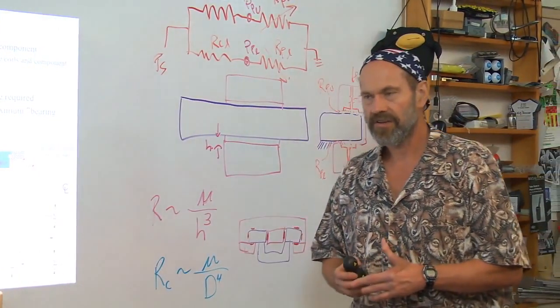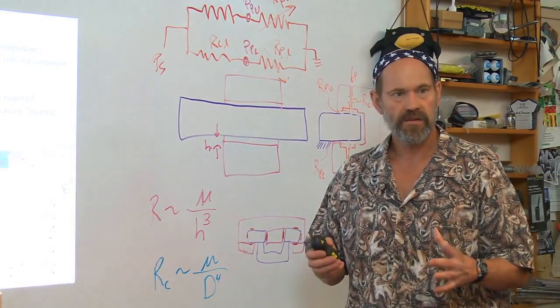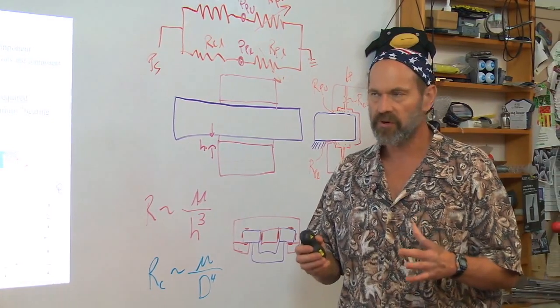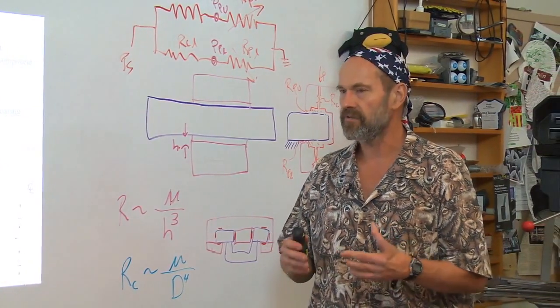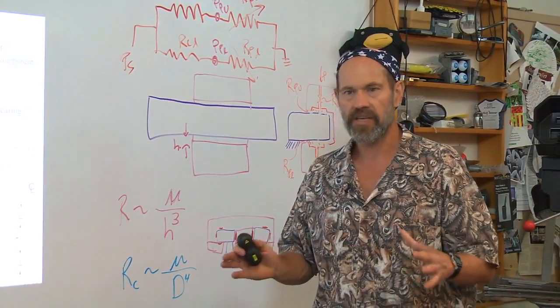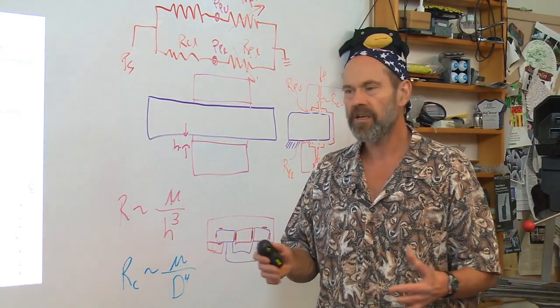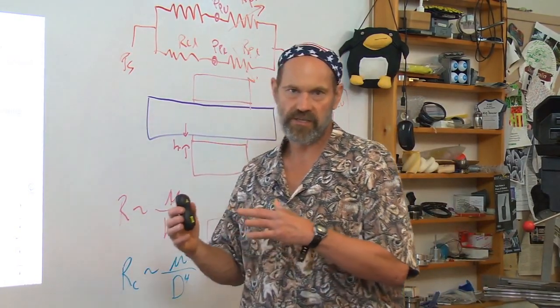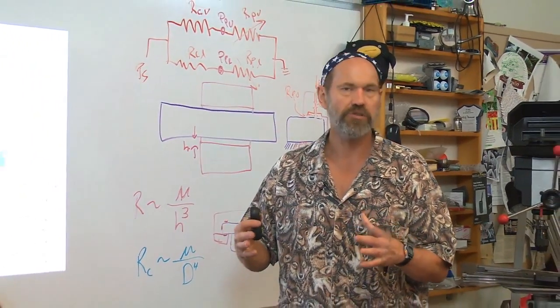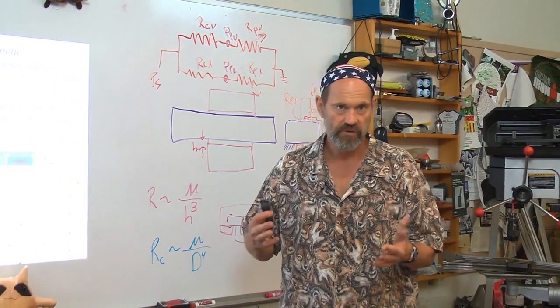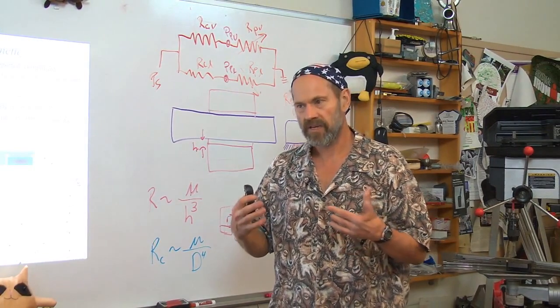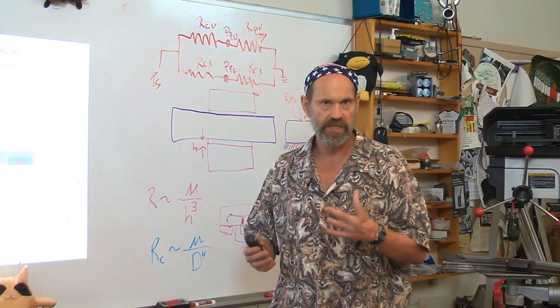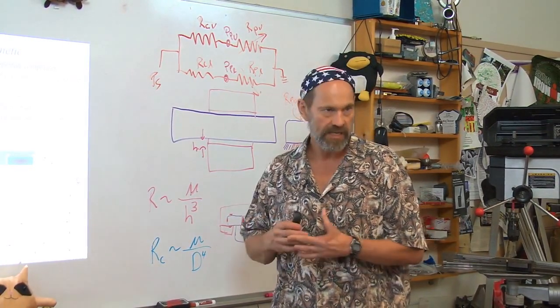Again, you can do anything with good engineering, which really boils down to a good accounting of keeping track of all the energy sources in your machine, how they cause the machine to deform, and thus create the parasitic error motions or undesirable motions that can affect the performance of the machine. That really is the name of the game of designing any type of machine.